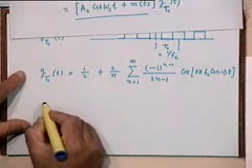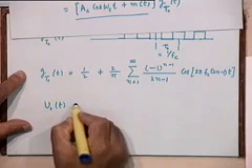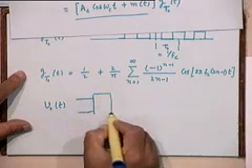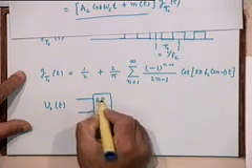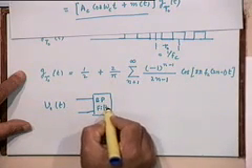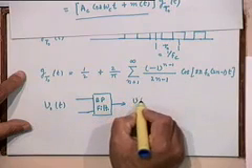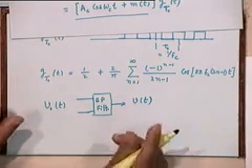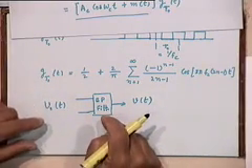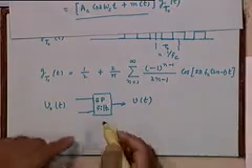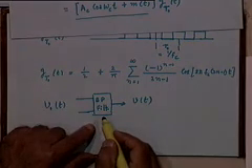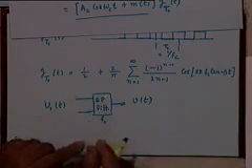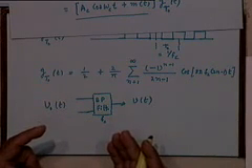So your v0(t) is coming here, you follow this up with a band pass filter, and the output v(t) will contain only those terms which are allowed by the band pass filter, right. Let us say the band pass filter is tuned to pass frequencies in the neighborhood of f_c, right.